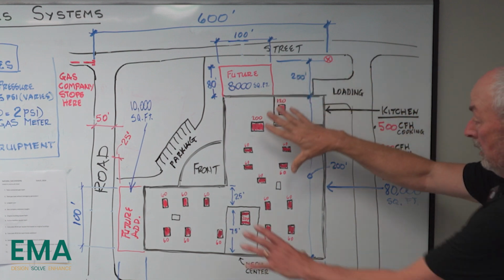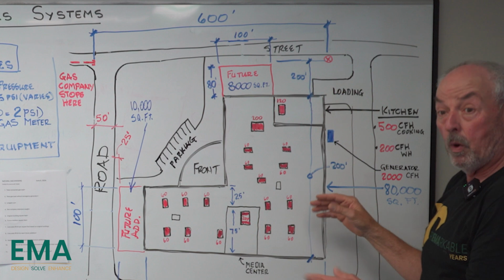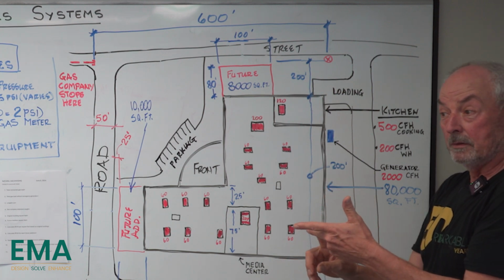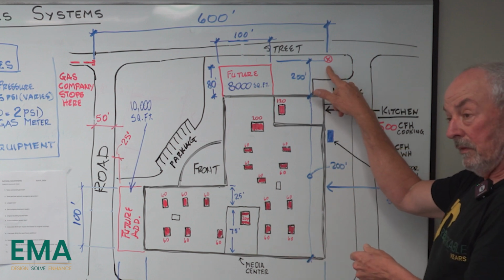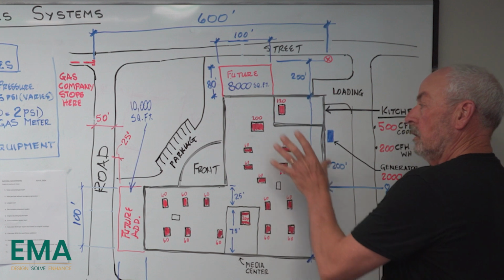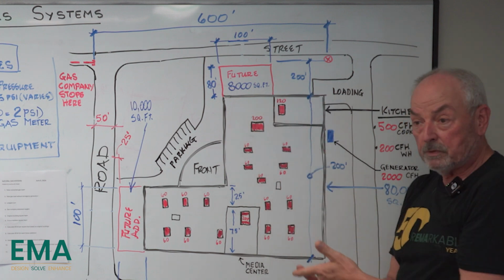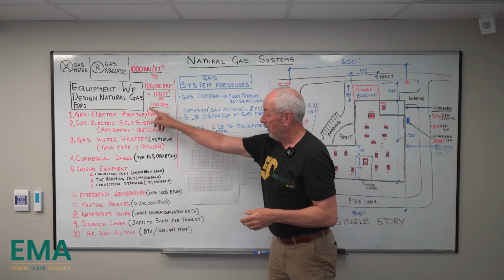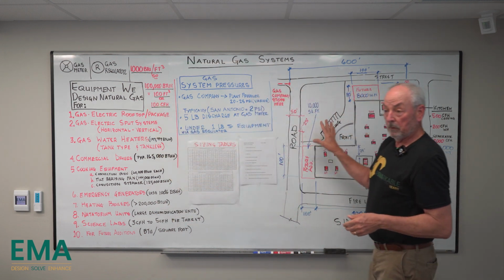and then we look at our load and we size it based on what we're going to talk about in a minute, gas load and longest run, and then that's going to help us determine the line size going to the building, and then we'll look at zoning what we're serving, rooftop units, water heaters, science labs, everything that's listed over here may vary depending on the building type.